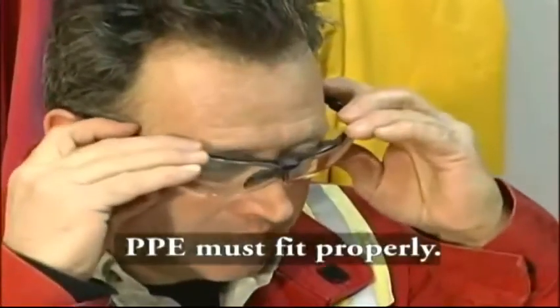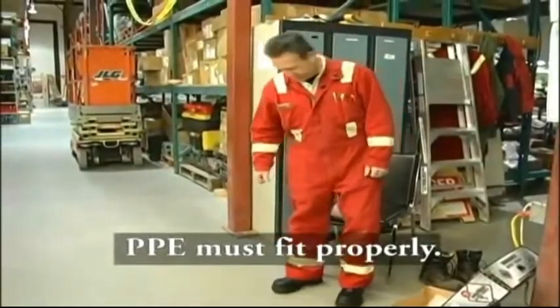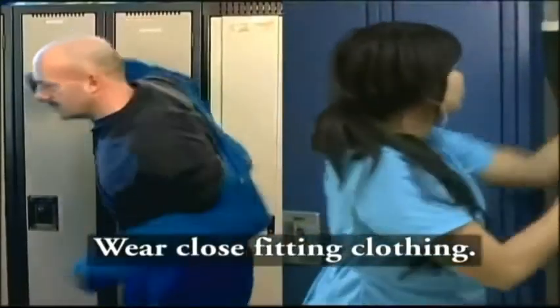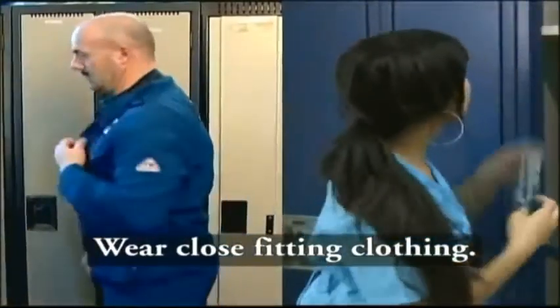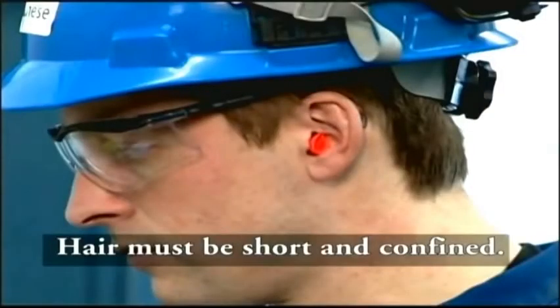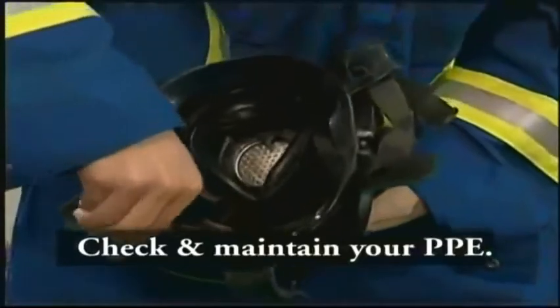Make certain your PPE fits properly. Poor fitting protection can create its own hazards. You must wear clothing that fits close to the body. No bracelets, rings, dangling neckwear, wristwatches, or similar articles. Head and facial hair must be short and confined to prevent getting snagged or caught in tools, equipment, or machinery. Always check and maintain your PPE so that it can function as intended.